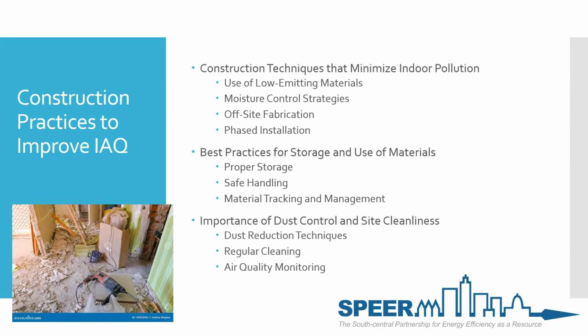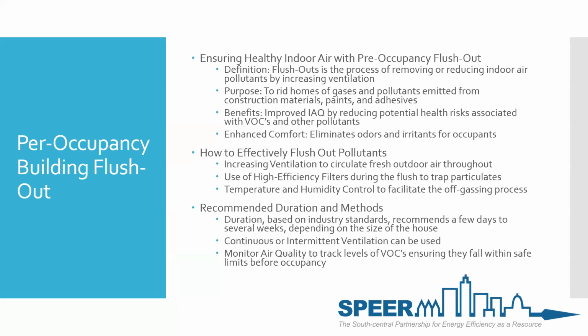And then air quality monitoring, we'll talk more about that later, but utilizing air quality monitors during construction to detect and address pollution sources promptly. I've never actually seen that being used, even if it's a LEED house. I think that's something you probably could do, but it's not that you have to do. And with LEED and Energy Star, they want the ducts to be sealed with some sort of method to not have contamination build up inside the ductwork. So they have to be taped throughout all of construction. So a lot of this stuff can be done. I just don't see it happening a lot, but more could be done to lower contamination and indoor pollutants inside of a house.